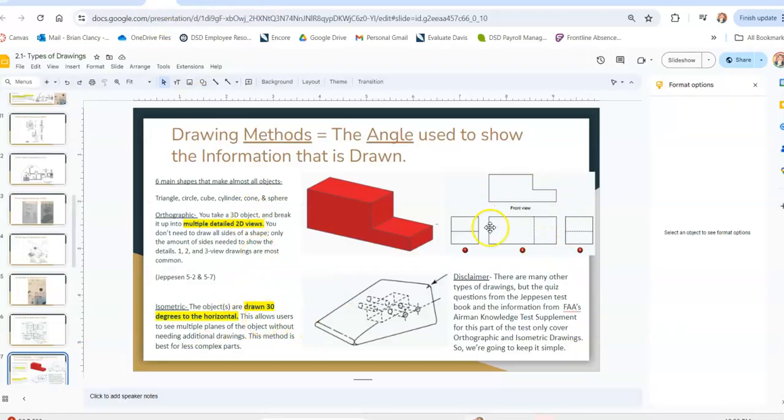And you're going to notice that these orthographic projections only show you one perspective at a time. Front, bottom, right, left. But over here on the isometric view, when you skew it at a 30-degree angle, you could see multiple faces at the same time, and that really helps you to get multiple pieces of information within the same view.